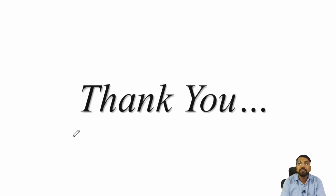So thank you very much. In this lecture we have seen how the three-dimensional heat transfer equation is derived with a metal block having x-directional, y-directional and z-directional temperature profiles with internal heat generation, and how the time term is there, and the time term is equal to 0 in a steady state. This three-dimensional equation we converted to a one-dimensional equation, and that one-dimensional equation we again converted to find the temperature profile at distance x.